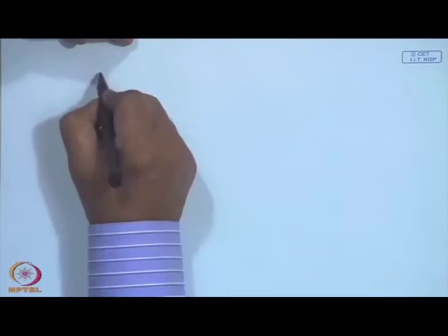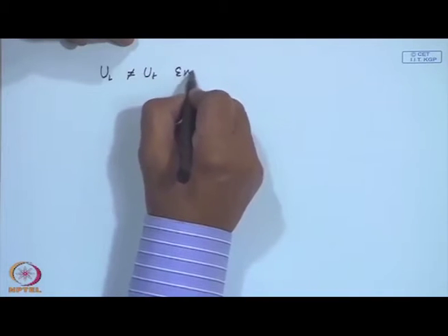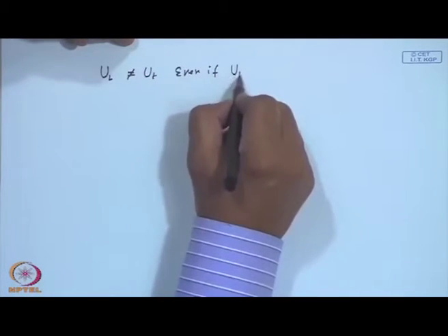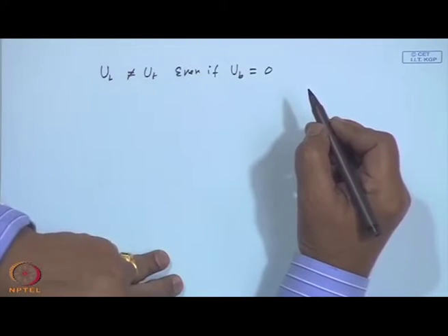Now, you can see from this equation UL is not equal to Ut even if bottom loss is 0. So, this is where it comes that the fluid is directly coming in contact with the top of glass plate where from the loss is taking place, and whatever the fluid is receiving, if you look at from the plate point of view, it is a Ut into something or a heat transfer coefficient into Tp minus Tf, which is also the useful energy gain.